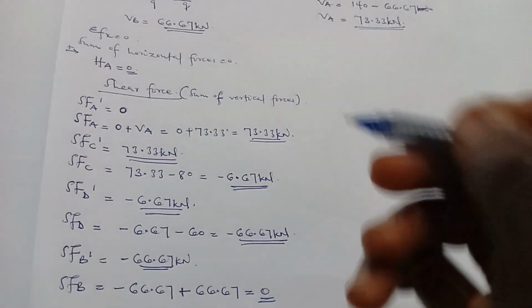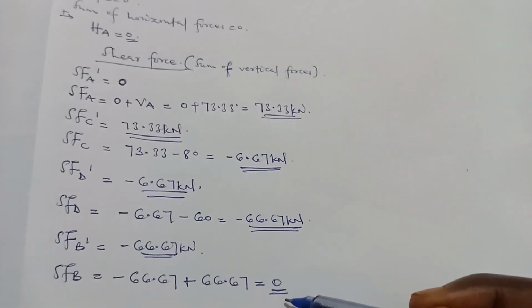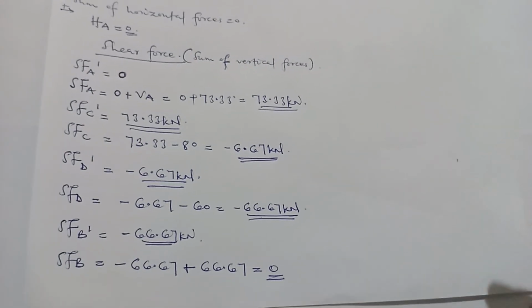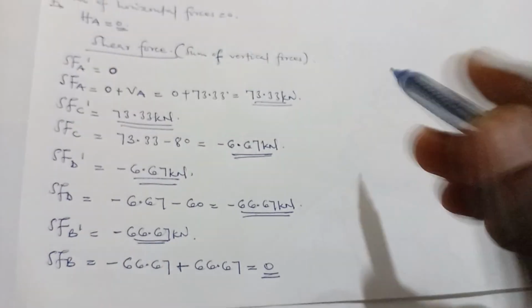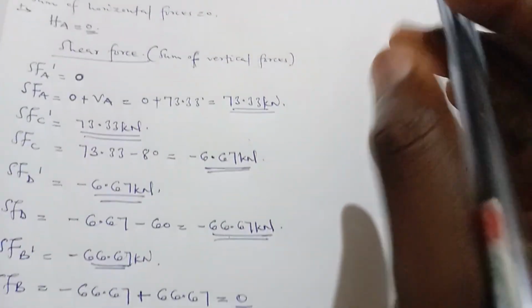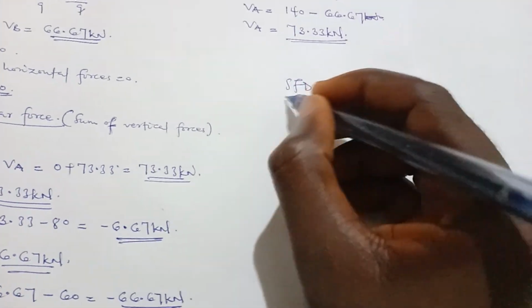Good. So like I said, you start from 0, then you end at 0 when it comes to calculations for the shear force. When you are drawing the shear force diagram, you start from 0 and it will end at 0. So after this calculation, we'll draw the shear force diagram.